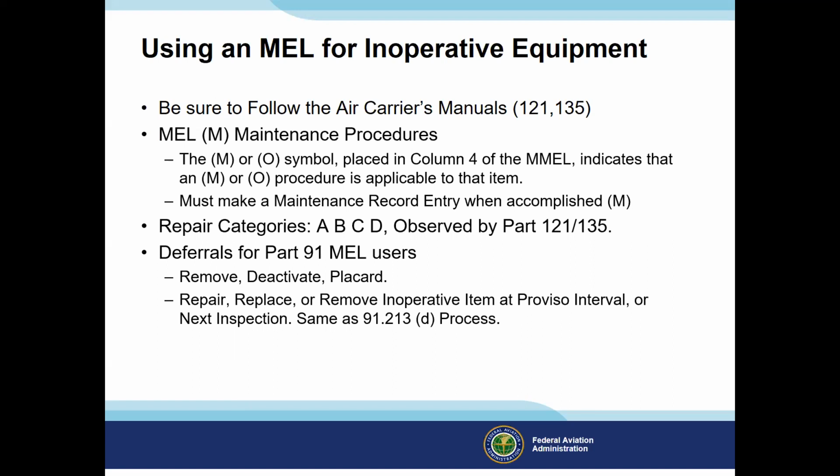Now, for deferrals for Part 91 MEL users, the repair categories don't apply. They have to repair, replace, or remove the inoperative item at the next inspection. Or if the proviso says before or after three flight days or something to that effect, they do have to follow an interval specified in a proviso. And this is essentially the same as the 91.213(d) process, where they remove it, or deactivate and placard.